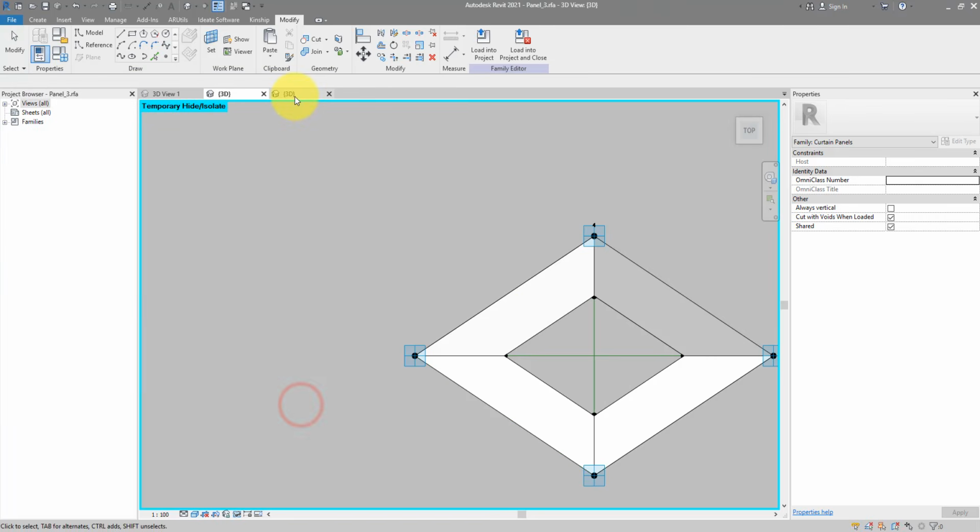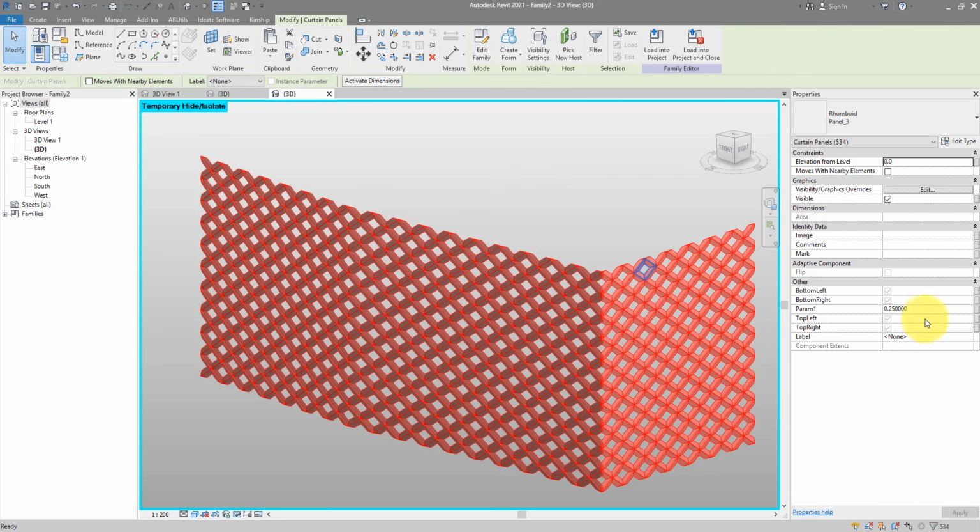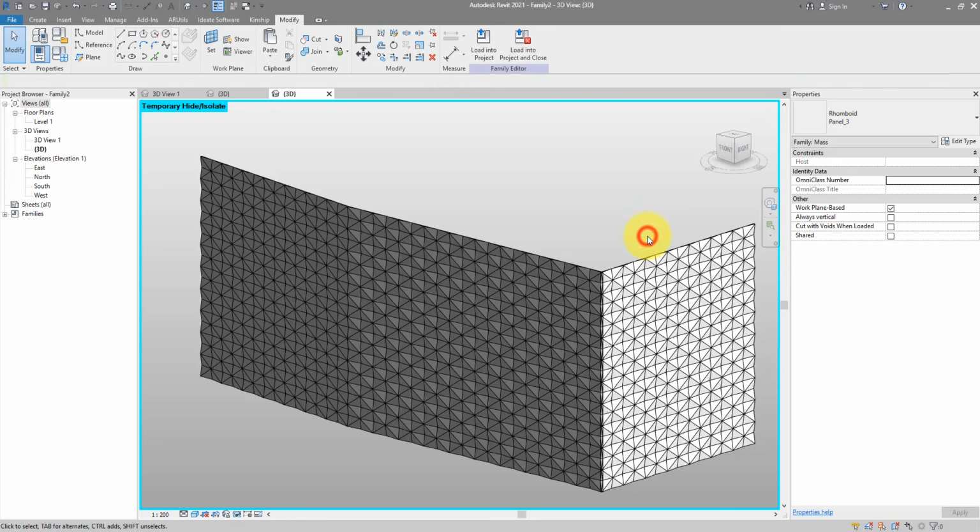That will mean that these 4 internal lines are reduced into a single point, which will generate an error. So, to get the panel to the closed position, we should go for something less extreme. That means instead of 0.5, we can try maybe 0.49. And that gives roughly the same effect. Alright, so far so good.